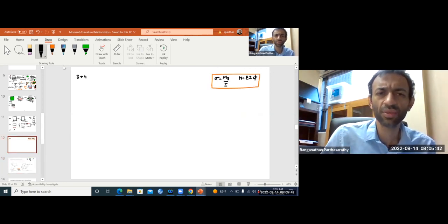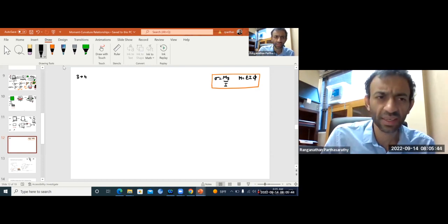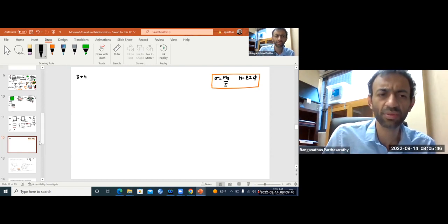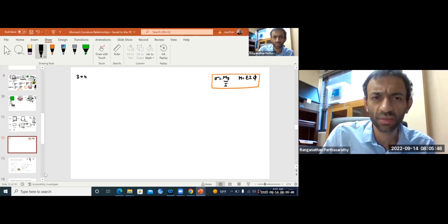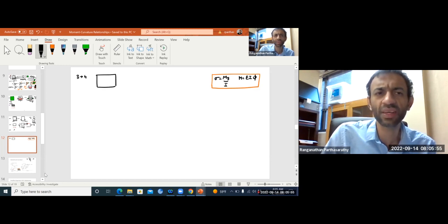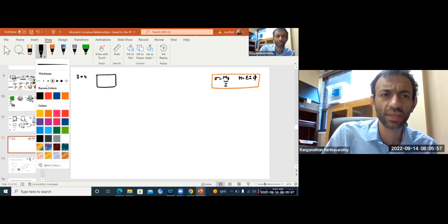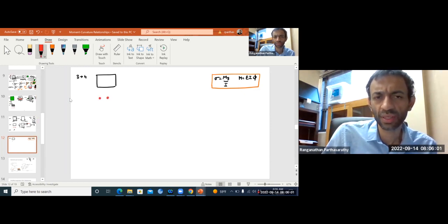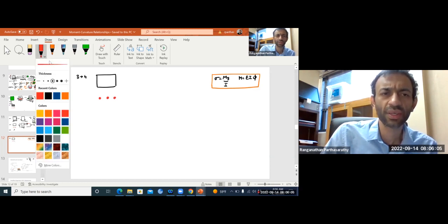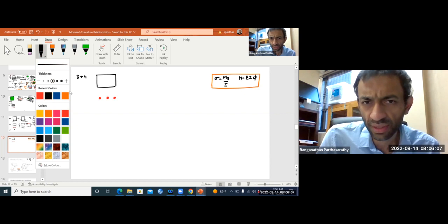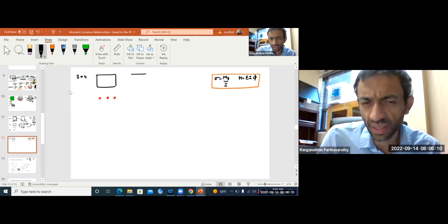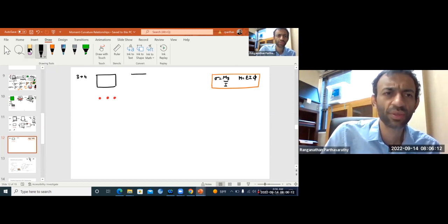We have to consider the exact stress-strain relationship of concrete. That means you have no more equivalent section business now. Here is your steel, and in your concrete, this part is already nonlinear.